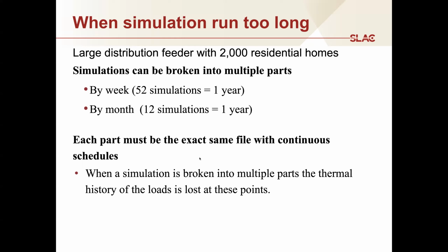When you do that, though, you have to be aware of the fact that the dynamics don't carry across from one state to another, and you would have to choose your initial conditions for each week or each month a little bit more carefully than you would in a year-long simulation, where the initialization transient might last only 2 or 3 days, and it doesn't really matter. In a week-long simulation, the initialization transient would take almost half of your simulation time.